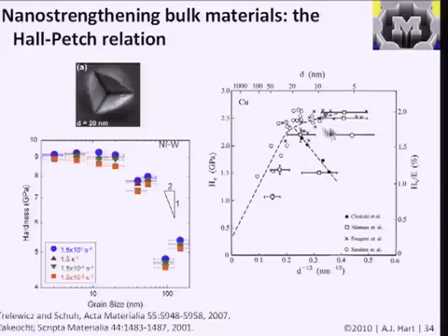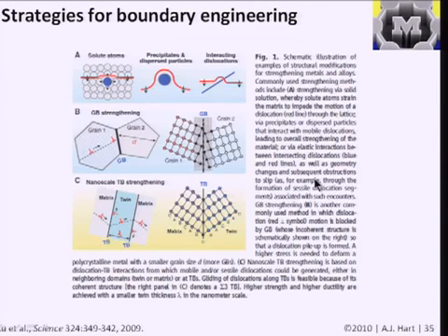And so this plot is kind of messy, but what we're seeing here is the hardness, which is in some ways a measure of strength, as a function of d, the average grain size. And we're seeing that as we decrease the size of the grain, we're making the material harder, and then there's a point at which things go the other way and the strength starts decreasing. And why this happens beyond the qualitative reasons I discussed is not something we'll study, but I just wanted you to see that this is still a very open and interesting area, and perhaps there's some interesting potential to engineer the characteristics of the materials.